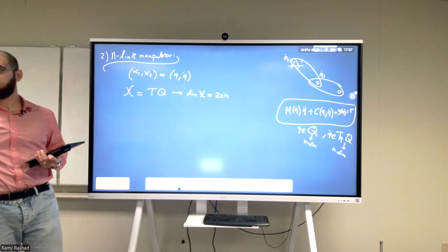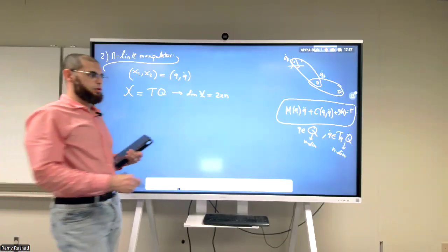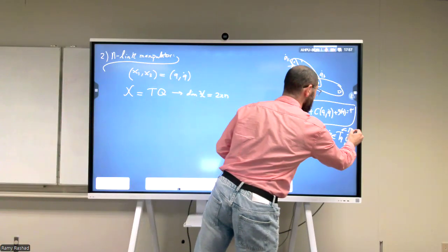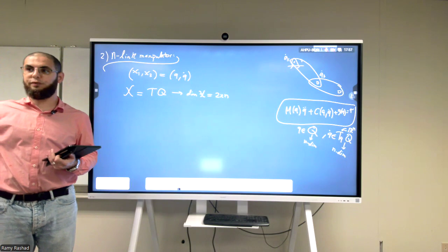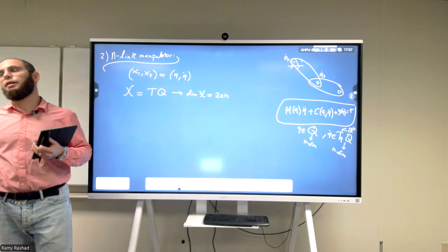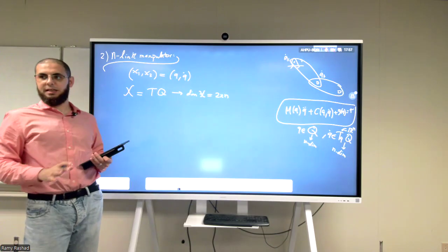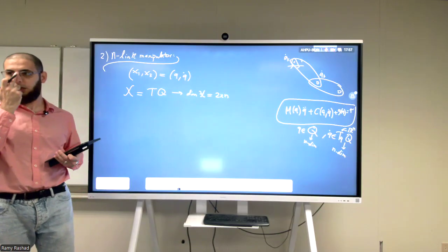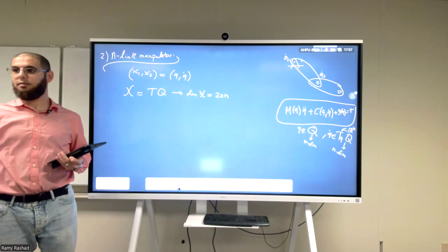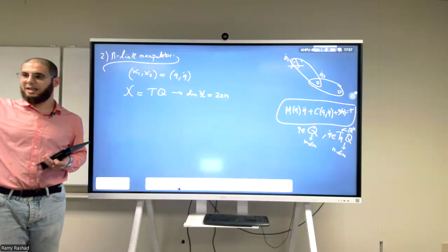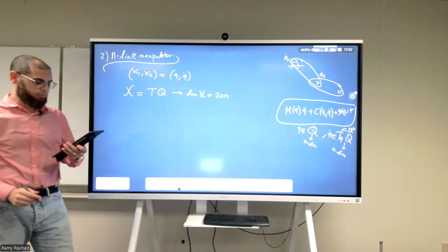The tangent space is isomorphic to Rn. Yes, it is also isomorphic to Rn, provided that you're using revolute and prismatic joints. If you have more complicated joints, for example spherical or nonholonomic joints, things become nasty. But in the simple case that we discussed, the simple kind of robots, yes, it's Rn. How you represent it mathematically is another story, but it will always be TQ, the tangent bundle.